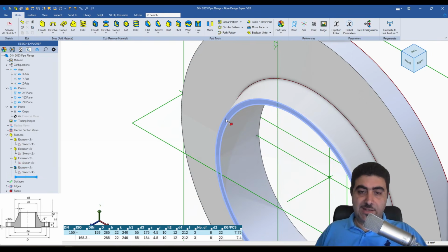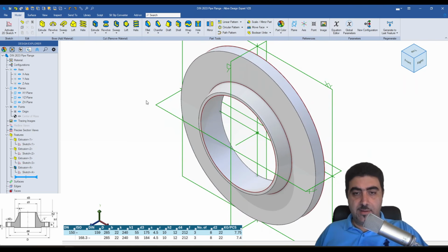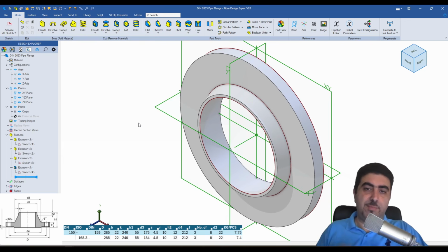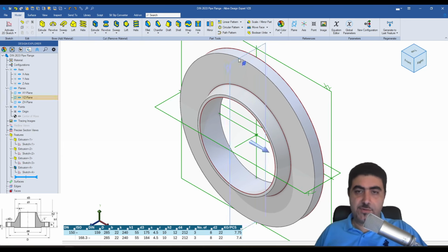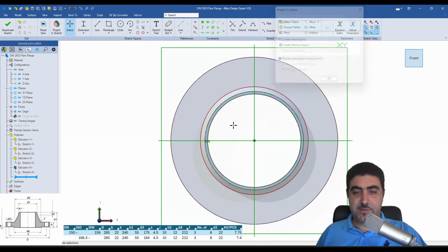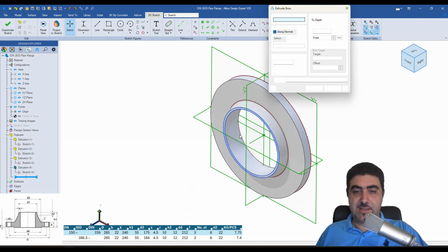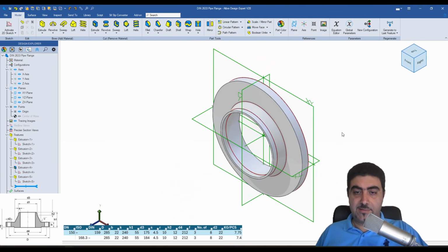Okay, in Fusion, we just clicked here and hit extrude, and it extruded it. That doesn't work in the extrude feature in Alibre, although it does work in the loft feature. So what you do is you do my imprinting trick. That makes everything a reference. You hit Control A to select everything, B to make it back into solid geometry, and then E, and now you're extruding it. There you go.